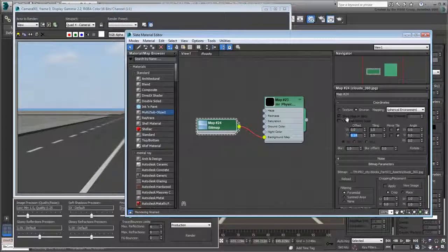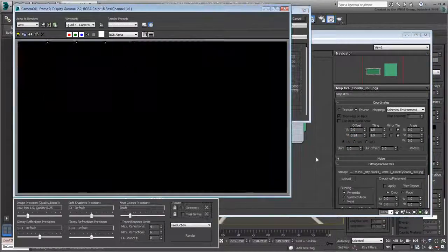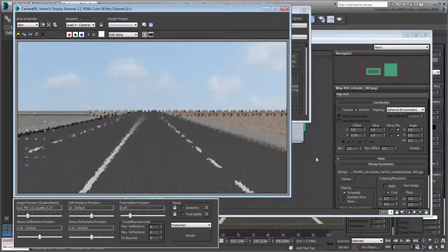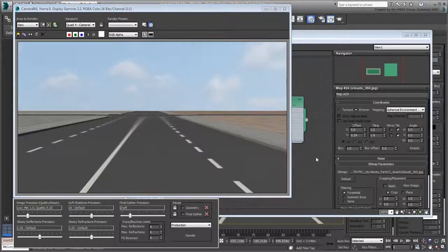Needless to say that a true 360-degree spherical map would work better, as you would not need to make those adjustments. However, they are harder to come by or create, so this will do for our needs. Next, you adjust the road markings and their distance blur properties. You can help by increasing the anti-aliasing quality, but that in itself is not enough and it does increase render time. The alternative is to adjust the bitmap